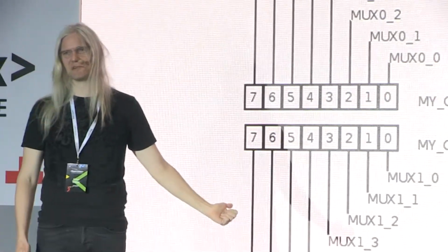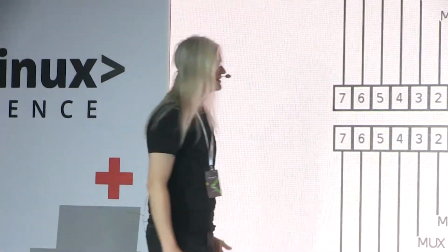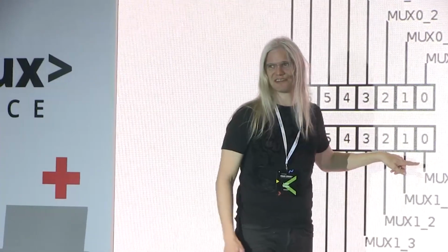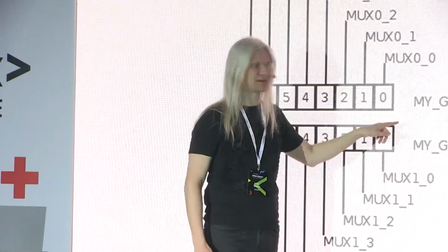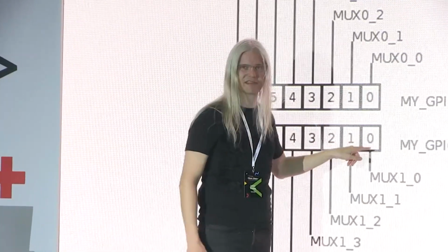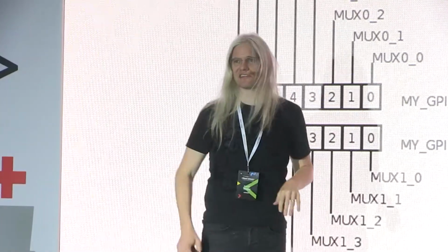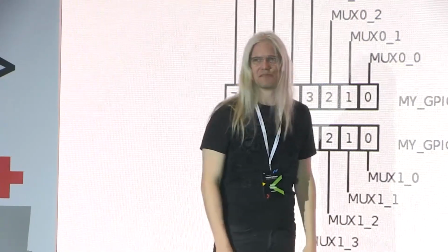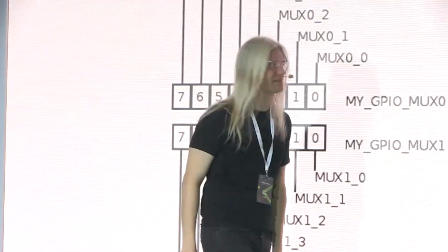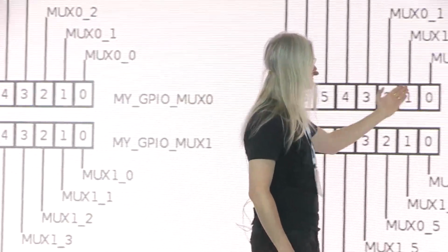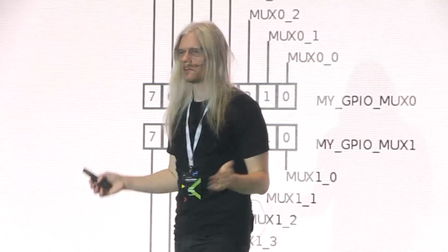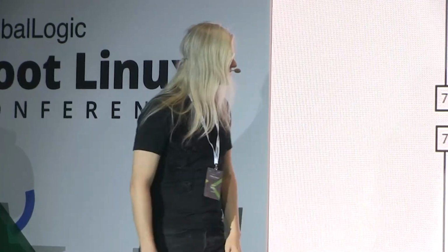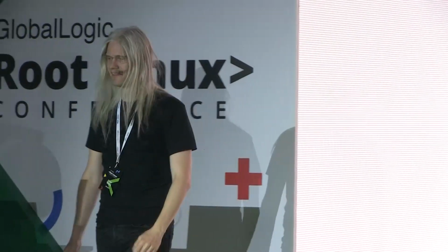Yeah, a lot of hardware engineers make this mistake, and we need to deal with it. If you write that register, this one has not changed yet. So your mux here goes through some intermediate state when you write this one and change that bit, and then you write that one and change that bit, and you get a glitch. That's what happens. So many chips out there with this mistake in them. So if you just put it like that instead, 2 lines like that, 2 lines like that, 2 lines like that, problem solved. Of course they get it wrong. So you find lots of interesting workarounds in the kernel for this glitch risk.